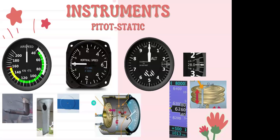Now, something that can happen more with the 172 than with the Cherokee is if we're in a certain configuration, such as a side slip, which for those of you who may not have done that before, is where you have kind of opposite aileron. So if you're turning your aileron towards the right, you're putting your rudder into the left.